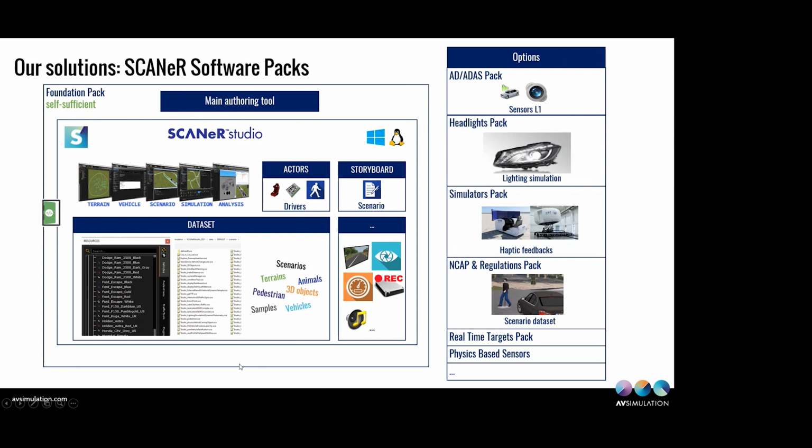This is the main tool in which you will be designing the terrain on which the simulation takes place, the vehicle, the scenario, etc. You will be choosing the different actors in the scenario, whether they are vehicles that are driven autonomously via our traffic tools, or vehicles that are driven with a driver in the loop in simulator use cases, etc., and also the pedestrians revolving around the car, the different other vehicles, etc. This is the main tool.